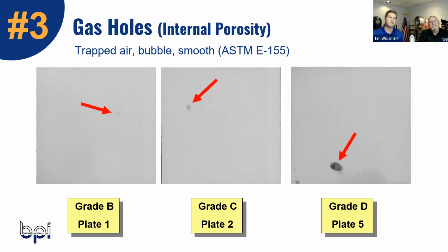They're almost always related to some form of metal turbulence. Okay. Monty, I think you had mentioned too, in our process here, this may be the most common porosity that we'll see. Depending on how fast the tilt pour is operating, it may hit bottom and cause turbulence in the bottom end before it goes into the casting. So is that why you pay very close attention to tilt times? Yes. And pour rates and the turbulence, as Ernie was just mentioning. Okay, so instead of making this a one size fits all, it sounds like it becomes very custom to the part. It is. It's individual.